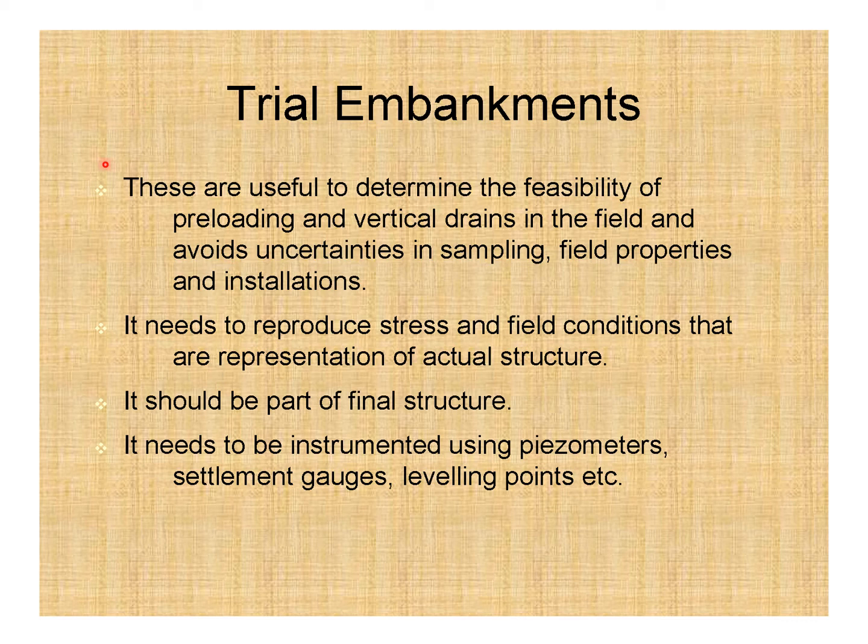Trial embankments. These are useful to determine the feasibility of preloading and vertical drains in the field, and avoid uncertainties in sampling, field properties, and installations. It needs to reproduce stress and field conditions that are representative of the actual structure. It should be part of the final structure. It needs to be instrumented using piezometers, settlement gauges, leveling points, etc.